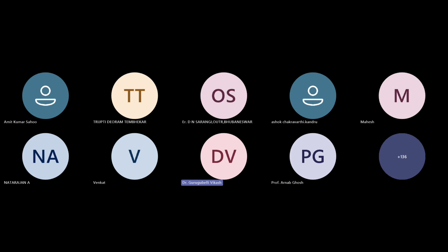You can connect them, but you have to use some other controllers that will maintain the DC bus voltage. These inverters can maintain only the output voltage and frequency set points. The DC bus voltage you cannot control by using VOC. For that, you have to use some other controller to maintain the DC bus voltage. If you maintain the DC bus voltage properly, definitely you can connect all these inverters in parallel. No issue. And you have to do some power management also.